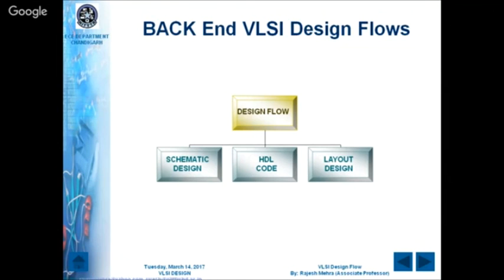Actually, in backend VLSI design, mostly we start with schematic, graphical. But again, it depends upon the availability of circuit. If you are working on some circuit and you are following some paper, and in that paper the circuit is in the form of transistors, then no doubt you are going to start your design in the form of transistors. If your input data is in the form of gates, then you are going to start your design creation in the form of gates. And sometimes your paper is based on some code. In that case, you have to start your design on HDL.